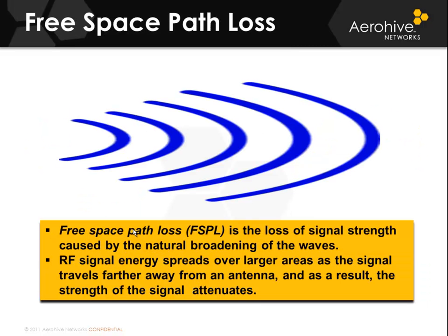Free space path loss occurs in every signal, even between laptops using an ad hoc network on the same table, although that degree of free space path loss would be minimal. Free space path loss is the loss in signal strength, or reduction in amplitude of a wave, that would result from a line of sight path through free space, meaning there are no obstacles causing reflection, absorption, diffraction, or other problems. This is what you would expect to see on a bounded network through cables.